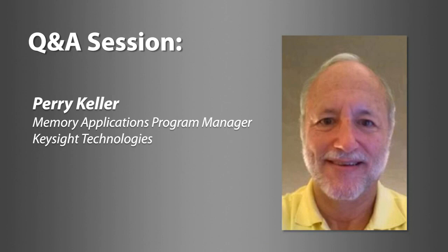Okay, here's the next question. Can you talk more about the distinctions between DDR and GDDR? Sure. So GDDR has always been a generation or two faster than DDR. The reason it's been able to do that is because it lives in a world where there are much higher power and cost budgets available to it.